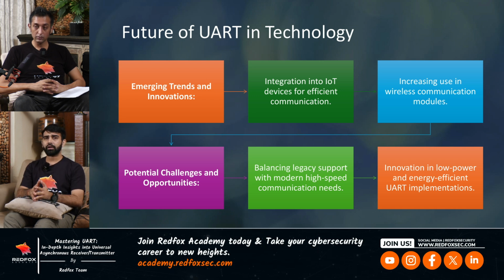Medical devices are bigger and more costly, so there has to be a backdoor UART or JTAG so they can communicate about where a problem occurs and how to resolve it. That's why they keep the serial communications.